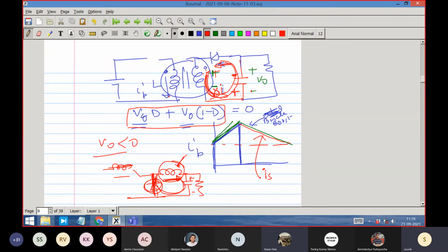Yes, yes. First thing you have to see is whether any energy storage element is getting continuity or not. In this case it is a coupled inductor, taking continuity with two coil currents together. At one time, one coil current can conduct. Then Q turning off forcibly discontinues that, and this energy will try to find another path, and it sees that that path exists in the secondary side.